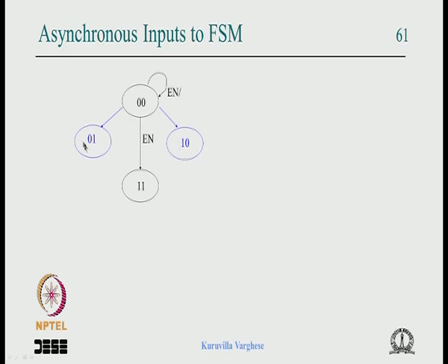state 1 0 or 0 1, and we don't know about this state, and this could be some state within the state diagram, or it could be an unused state, whatever it is dangerous. This is not like output races where it goes briefly there and comes back, it really mistriggers. So you can imagine that you have a very complex state machine which loops and branches and all that. Suddenly you find that it is in some state, and soon you find that the state machine is elsewhere and it continues from there, and it is quite dangerous.